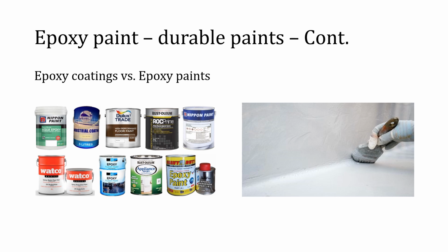The main difference between epoxy paints and industrial epoxy flooring is that epoxy paint is only suitable for light-duty application and has never been intended to be used for industrial use. In contrast, epoxy floor coatings are durable, industrial optimized resins that are designed to stand up to high traffic usages. Epoxy floor paint is more durable than traditional latex paint, but it is not as durable as epoxy coating.